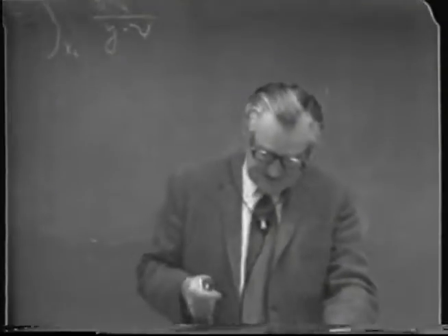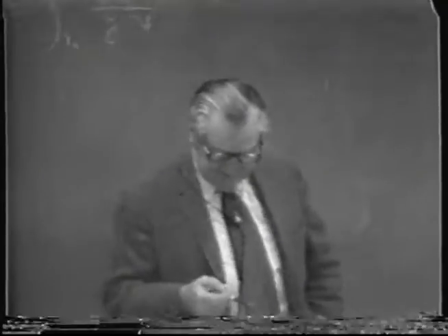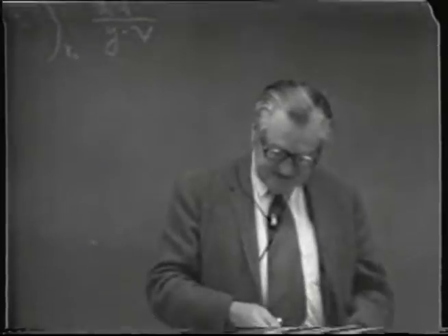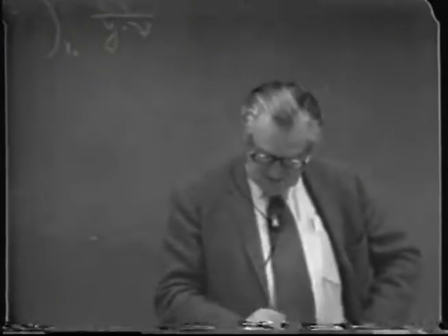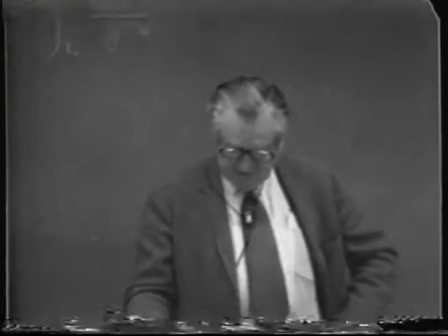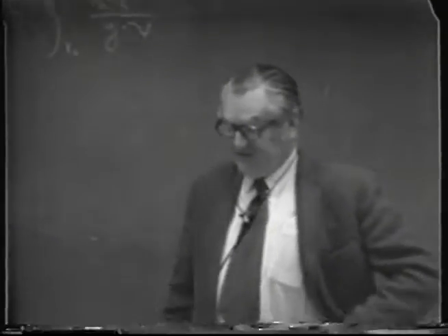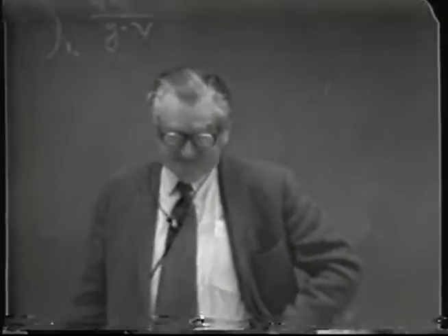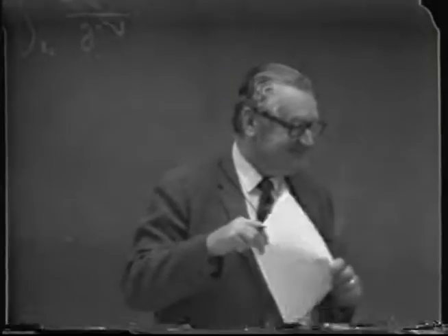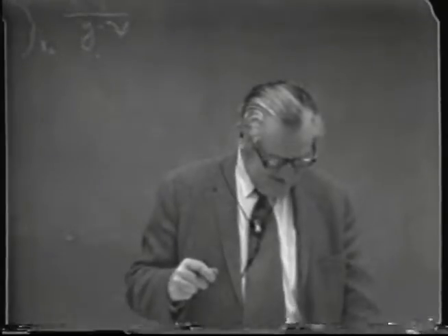In practice, we routinely distill off about 10 times as much. So I solved it, but didn't show the solution here down at the bottom. The corollary would be if V2 over L is 10 to 1, then X1 over X2 comes out to be about 1,040 to 1, which gives a percent recovery of 99.9%. So in other words, that's adequate for the analytical procedure.